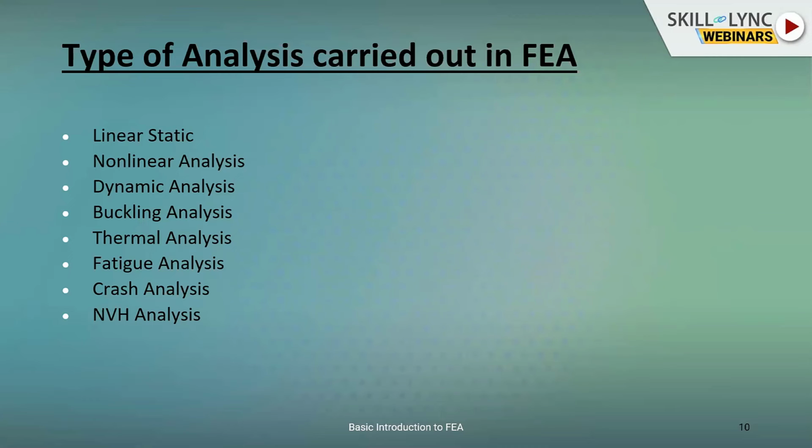For that kind of scenario, linear static analysis is very helpful. Then nonlinear analysis is the analysis in which the load is applied incrementally in the software. The force versus displacement relationship is not linear in this case.